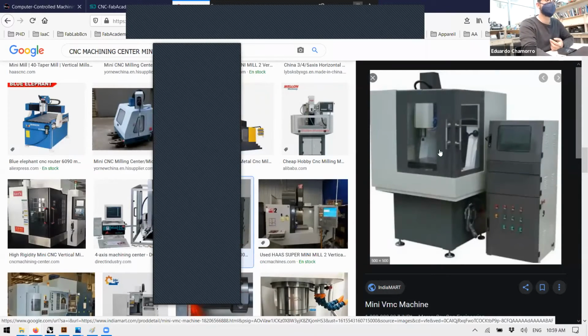The working area of this is really small, like 30 by 30 by 30 in general. The machine is huge because first it has water cooling, so it needs recirculation of fluids, and it has a stronger motor. Usually it's a 4 or 5 axis machine. This is just the control box with all the electronics isolated. These machines usually have a marble piece on the bottom, just to make it heavy so it doesn't move. The structure also has huge, ultra reinforced metal frames, so the machine doesn't bend even a little bit when cutting.